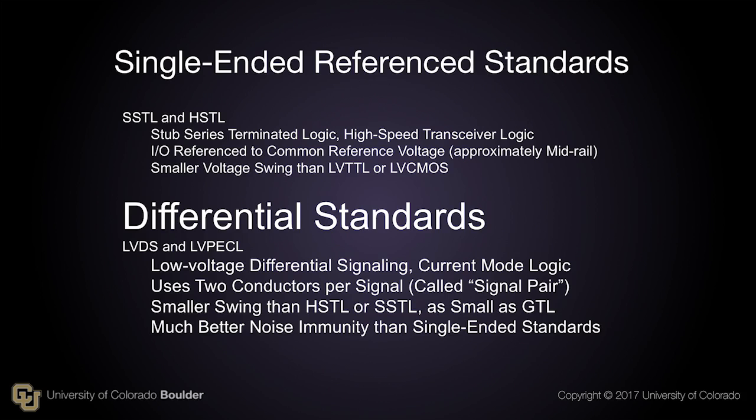So can you get increased speed and better noise immunity at the same time? Yes, with differential logic standards like LVDS and LVPECL. However, this comes at the cost of needing 2 pins for each signal. Use of differential logic standards is a growing trend as the speed of interfaces continues to increase.